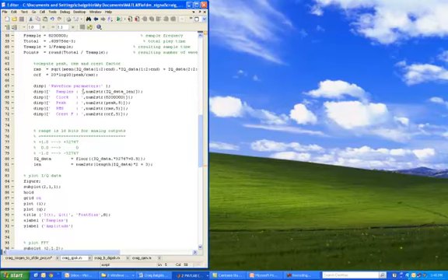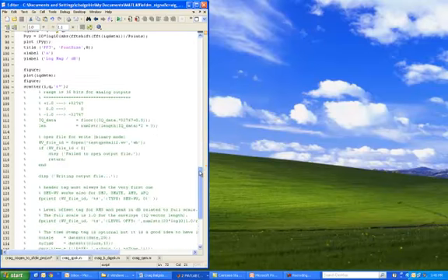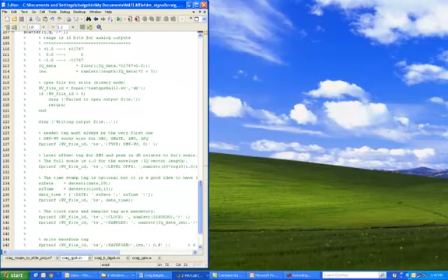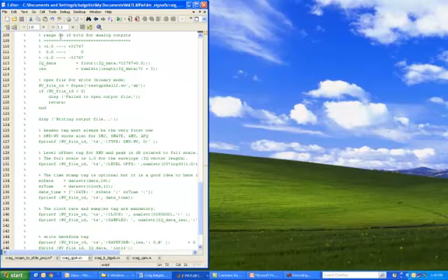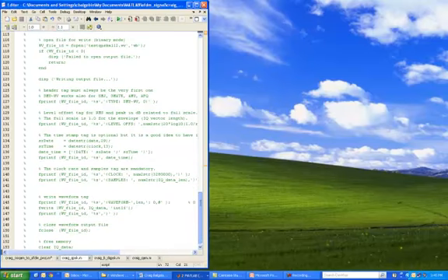I was able to get the crest factor of the waveform, and this is needed for the scaling. The DAC of the signal generator is a 16-bit, so you have to scale it to 16 bits so that it doesn't clip.